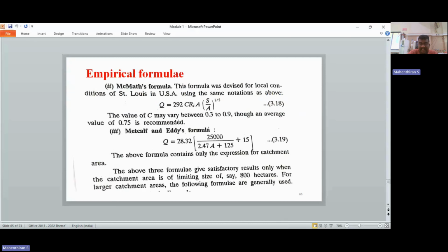This suggests that the St. Louis catchment used for calibration included some highly permeable surfaces, perhaps sandy soils, forest, grasslands, or agricultural land, where runoff is only 30% of the rainfall. Second, the recommended average value of 0.75 is slightly higher than the Berkeley-Ziegler 0.7. This indicates that typical St. Louis catchments might be somewhat more impervious than the catchments used for the original formula.